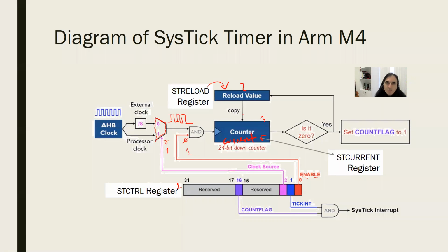This is something embedded programmers always use because it's a nice schematic of what the whole system is about. You don't have to check the bits and datasheets. It's written all over here. For example, bit 1, the second bit from the left, was the interrupt enable bit. This system creates an interrupt when it hits 0.